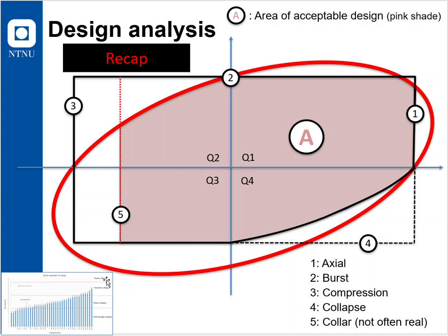Elastic collapse, typically for the larger pipes, doesn't obey yield criteria, so it's a straight line. It's also at the same time the weakest of the collapse resistance modes. So, to make this very pedagogic, it should be up here.